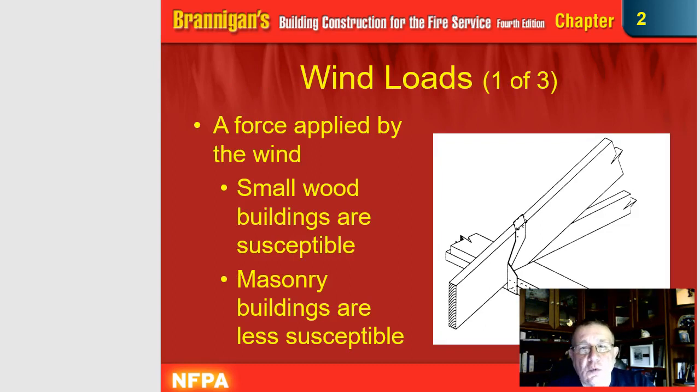One of the biggest things you got to look at, and this is one of the things you see, is a wind load. Today's building construction has to deal with a hurricane rating, and you start seeing straps applied to roof trusses that tie the roof truss itself to the top of the beam or the top of the column, or what we would call in this case the wall, and it ties it all into place. And what it does is keep the roof in a situation where, if the roof has a wind load that comes up, it brings it right back down. It doesn't lift off.